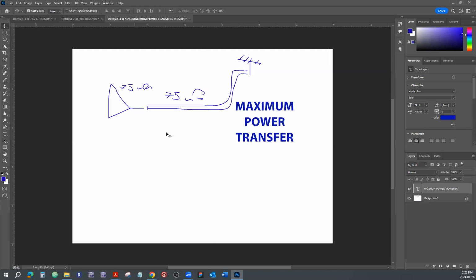If you have a 50 ohm characteristic impedance cable, then you need a 50 ohm amplifier, or the transmitter, which is the amplifier on the end, a radio frequency amplifier. Everything has to be 50 ohms. Right? There are two basic characteristic impedances for coaxial cables: 50 ohms or 75 ohms. That's it. Right? Unless there's something I don't know.